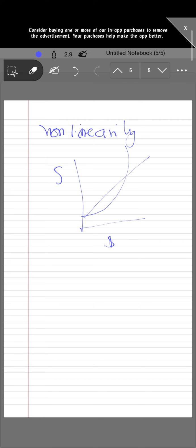So in that case, we need to find out first the midpoint on the x-axis, which we represent by xm. This midpoint is the maximum of x minus the minimum of x, divided by 2, plus the minimum of x. So this gives the midpoint of x, and the line connecting the endpoints represents the total amount of nonlinearity, which is calculated as the percentage linearity.